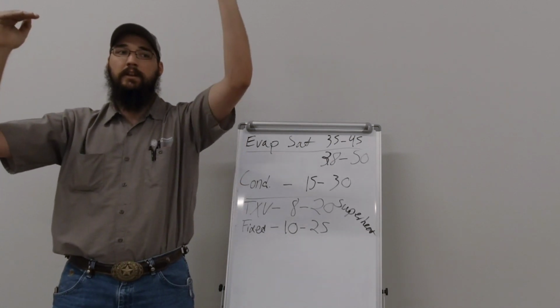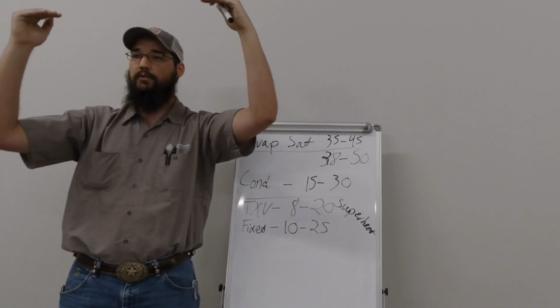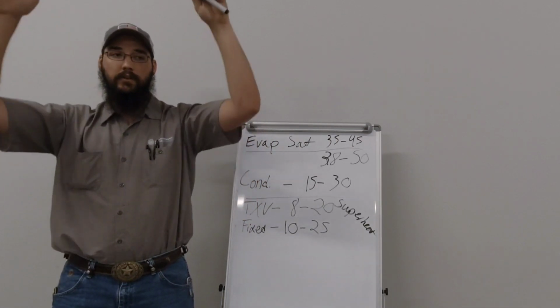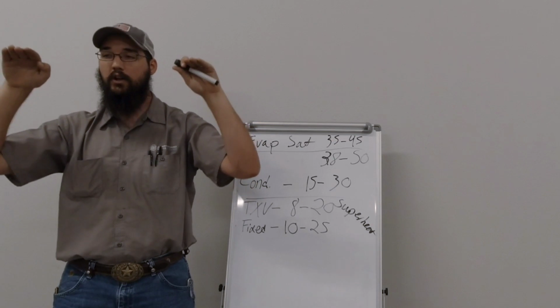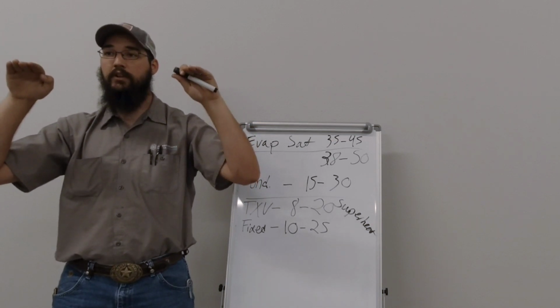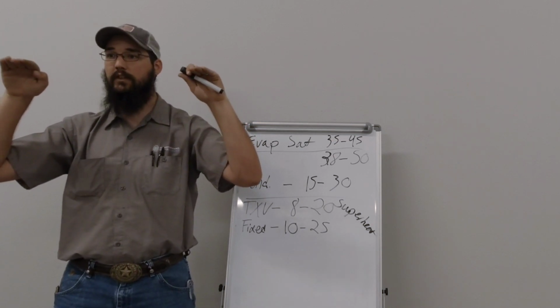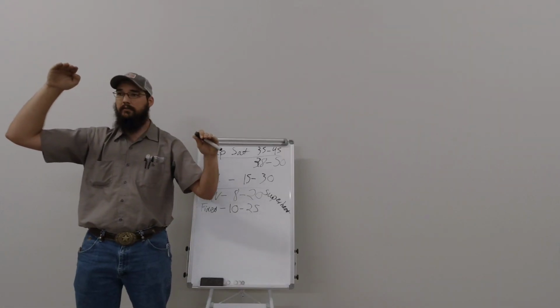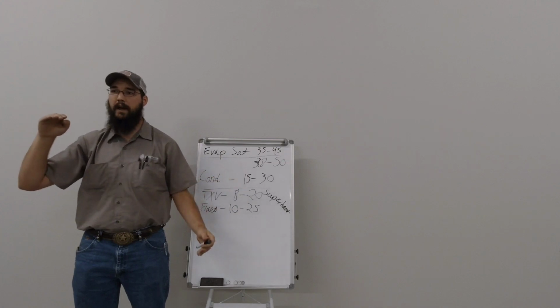As load comes down, superheat and saturation come down on the evap. So does the condenser and the subcool. They will track together, but they're only going to go so far. Eventually, if it's overcharged, which is easy to do, having too much refrigerant in there is going to start overpowering that fixed bore, and you'll start flooding back.